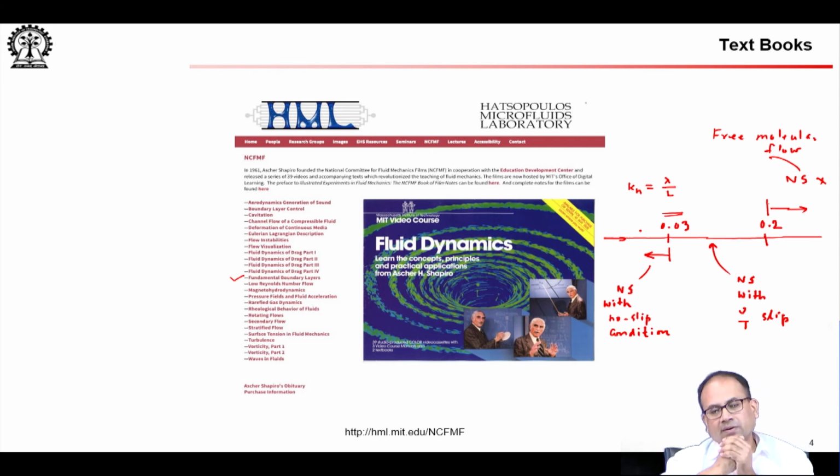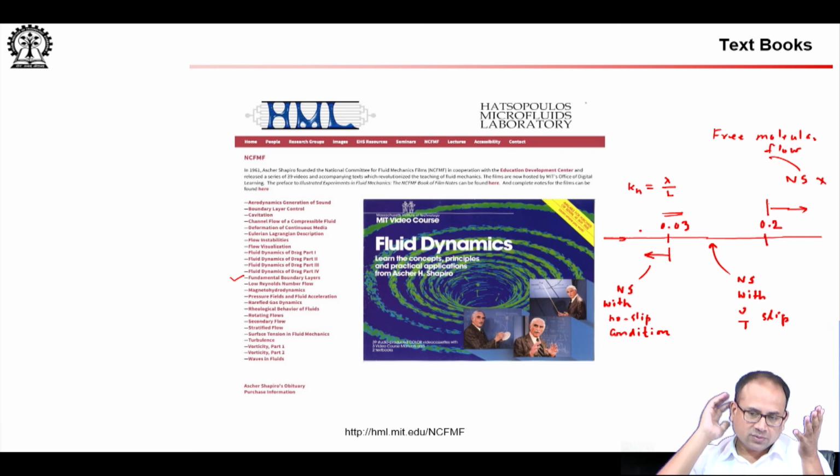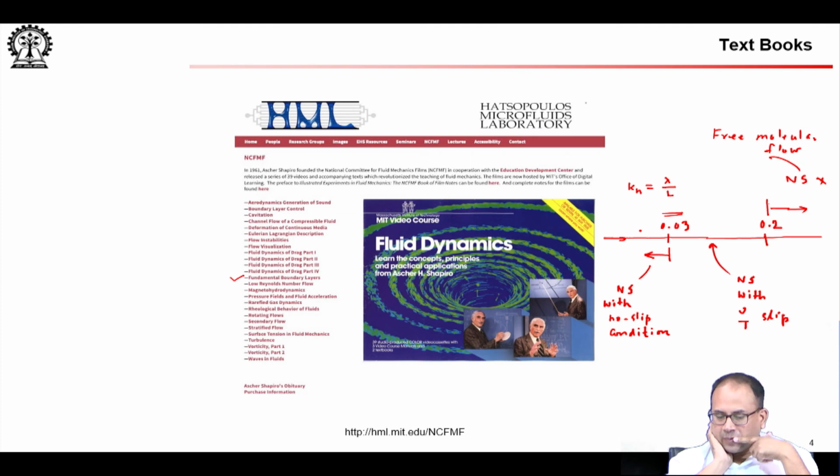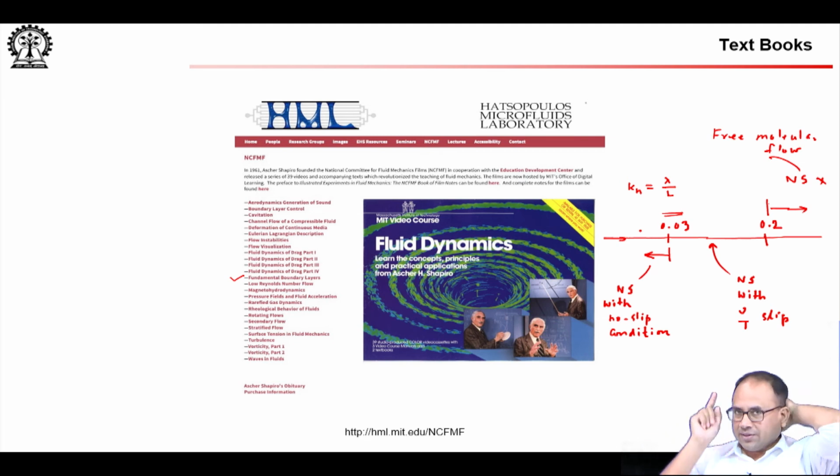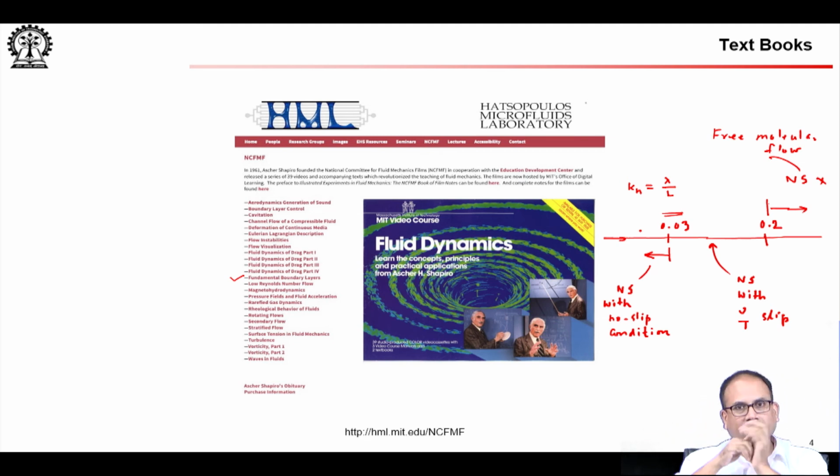Okay. You cannot just run the conventional approach that we would do for aircraft flying at 32,000 feet or even 85,000 feet. I think as high as 200,000 feet, your mean free path is about 10 to the power minus 3 feet, which gives a Knudsen number of 10 to the power minus 5. So, even at a height of like 200,000 feet, the SR-71 Blackbird that I showed in the first slide can fly up to 85,000. I am sure it can fly even higher than that.